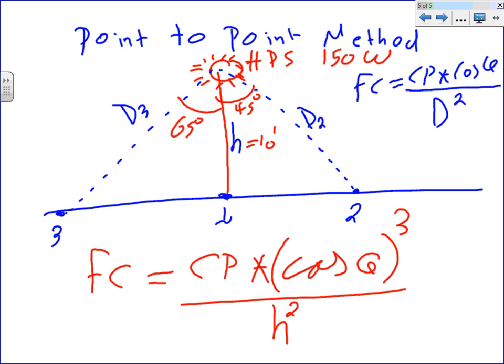These two formulas are identical. These two formulas, DJ, my friend, are completely identical. This one is superior because we don't have to find the D. It's always a function of the height. And Ryan, I always know the height of the fixture because I'm the designer. It's the 33-foot pole that I'm going to put this fixture at. But you don't always find the distance from the 33-foot pole light all the way to the parking lot. I know the angles. I can find it at different angles. Anyway, so the second one is the superior one.